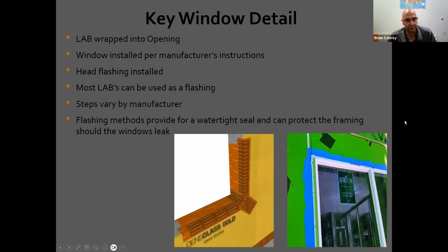What this looks like is this. Down here, the darker orange material is going to be the fabric membrane material that's fully encapsulated into the actual roll-on or trowel-on liquid material, which is the lighter orange. On the other side, the blue is in the window jamb opening.